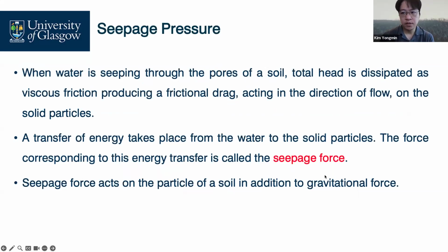So this is the last topic, but the first topic for our boiling and quick conditions issues. The energy transfer takes place from the water to the solid particles, and the corresponding force is called seepage force.